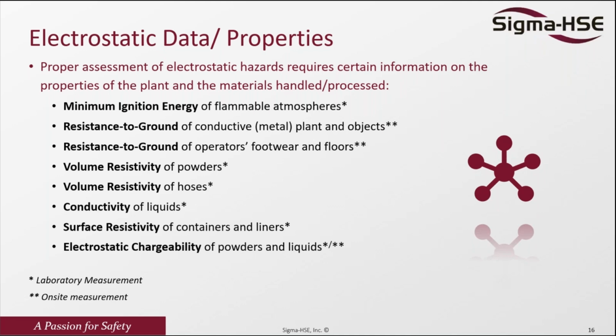I need to know, in the case of operators, what is the resistance to the ground of the operator, the footwear, maybe the gloves that they use. What is the resistance? Is it static dissipative, is it conductive? I need to do all these kinds of measurements.